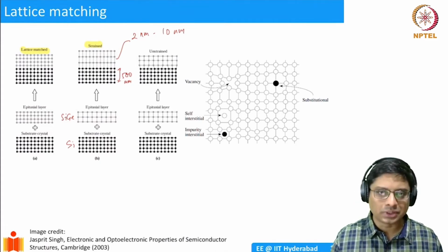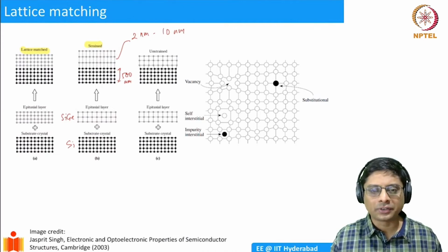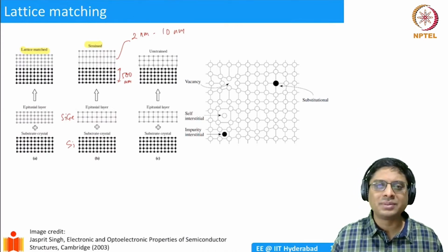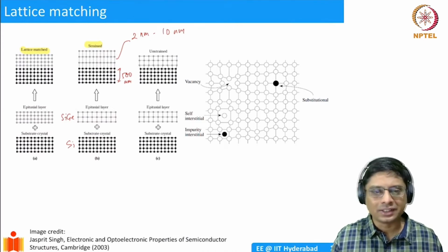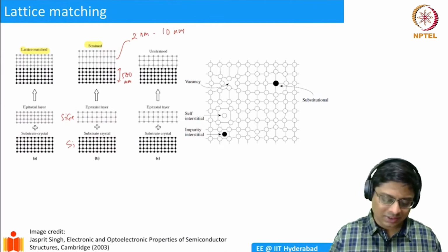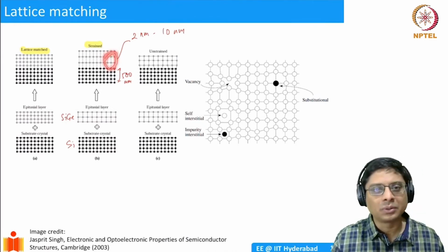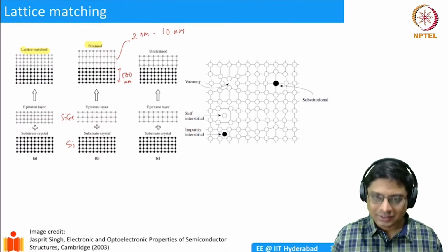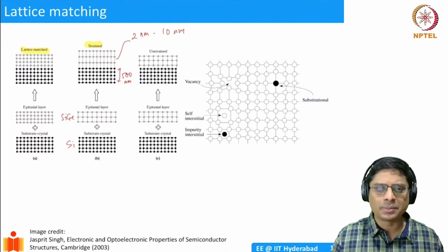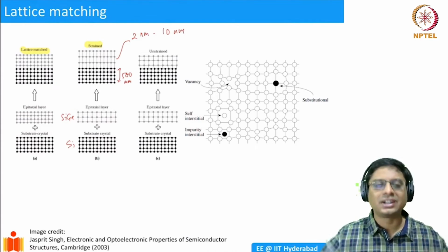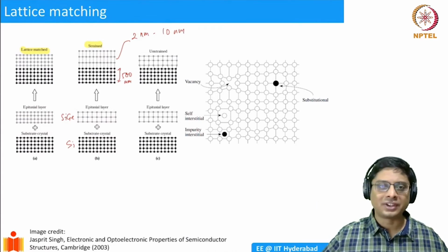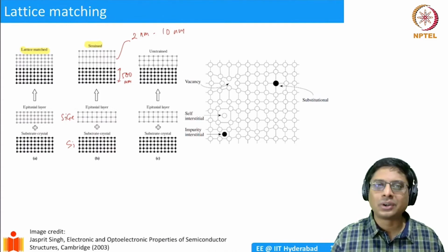You're able to grow. Okay, if you want a perfectly pure silicon germanium, then you have to use the entire substrate differently. And if you try to grow very thick materials here, invariably what happens is this will have some, what we call defects. What is that? Well, suppose this strain is not happening, somehow the lattice configuration is such that, let's say you're trying to grow gallium arsenide on silicon, the lattice constants are completely different, then it will not work.